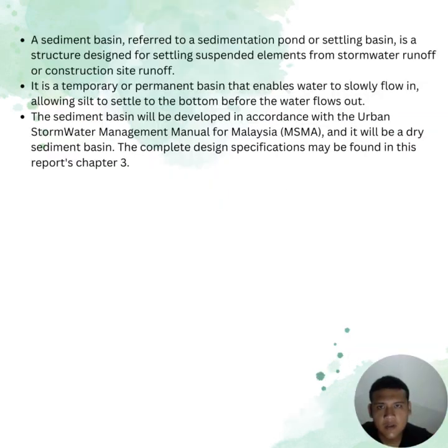So next is the sediment basin. A sediment basin, also referred to as a sedimentation pond or settling basin, is a structure designed for settling suspended elements from water runoff or construction site runoff. It is a temporary or permanent basin that enables water to slowly flow in, allowing silt to settle to the bottom before the water flows out. The sediment basin will be developed in accordance with the MASMA, and it will be a dry sediment basin. The complete design specification may be found in this report, Chapter 3.